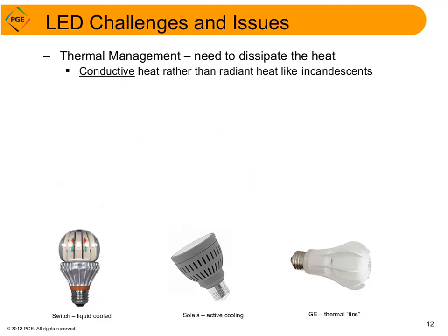So as a new light source, LEDs have several challenges and issues, and I'll go over some of these. So again, all LEDs produce some heat, and that needs to be conducted away from the source in order to operate efficiently and also to make them last longer. In LED bulbs, there's different ways of doing this.